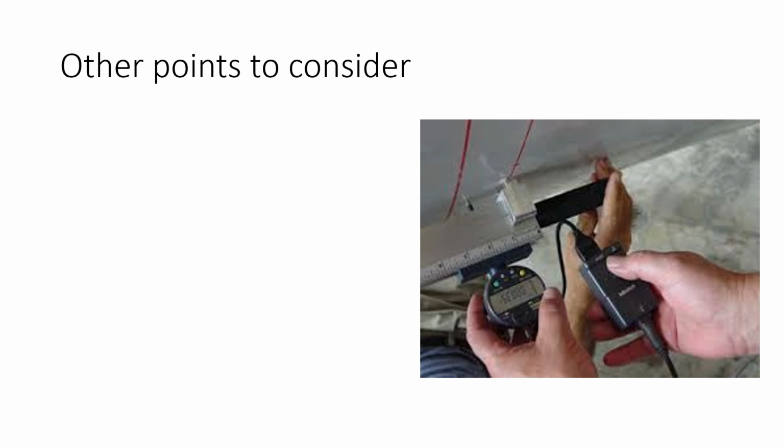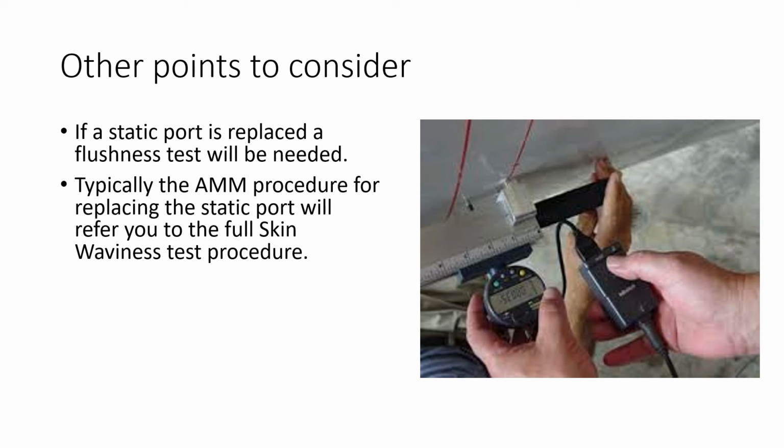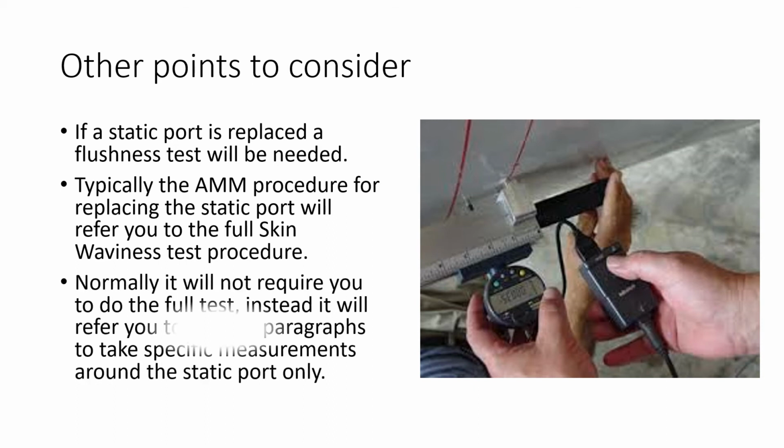Okay, some other points to consider. Now, if a static port is replaced, you will need to do a flushness test on the static port after it's been fitted. Typically, the AMM procedure for replacing the static port will refer you to the full skin waviness test procedure. However, normally it will not require you to do the full skin test.